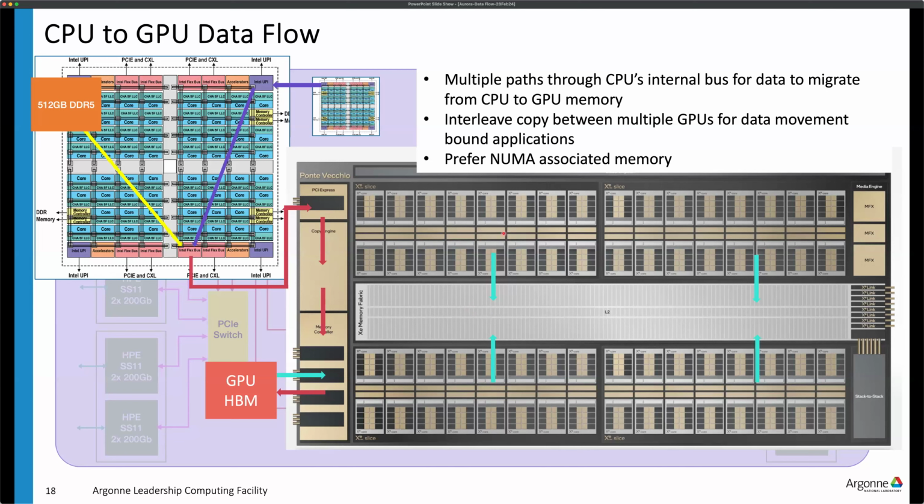In addition, within the GPU as well, if data movement needs to happen, it uses this fabric that has connectivity across all of the different slices and the different compute units. So that is also a key thing to know, because there is a limit to how much bandwidth you can operate on the fabric itself. Again, these are all things that you will notice if your application is extremely memory bound and latency sensitive rather than throughput based, right? But this is a common limitation for any GPUs that exist.